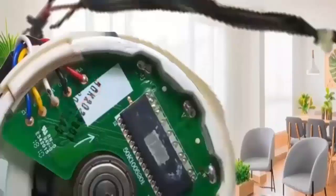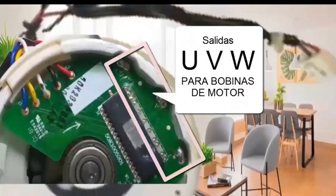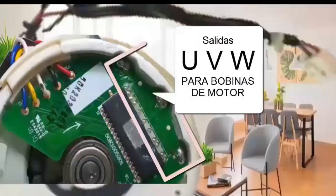5. The fan motor can be removed and its casing opened to check if power is reaching the motor internally. Visually inspect the internal electronic board of the BLDC motor for anomalies and check for continuity across all wires from the fan connector to the input of the motor's electronic board.